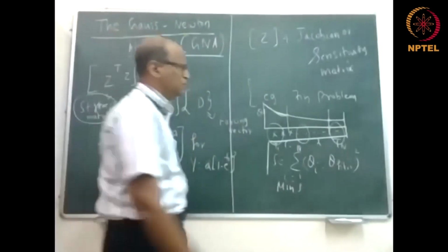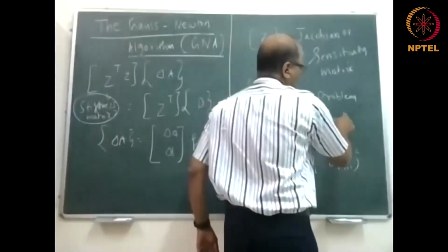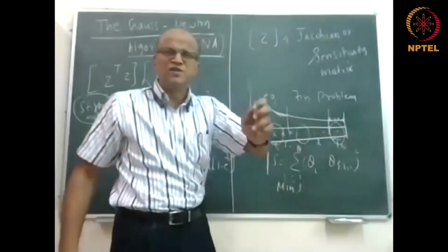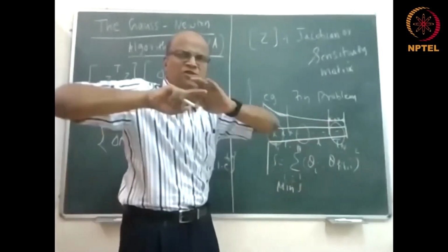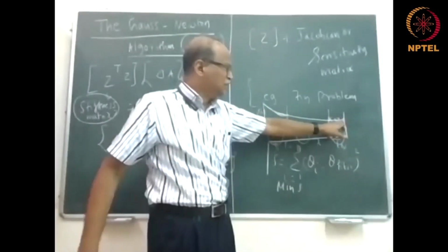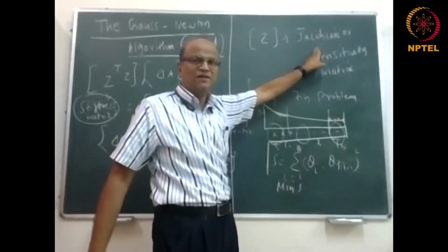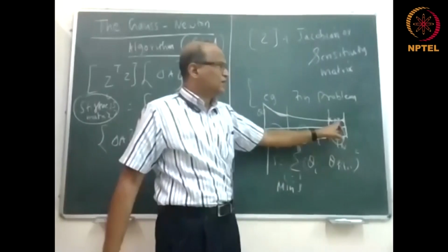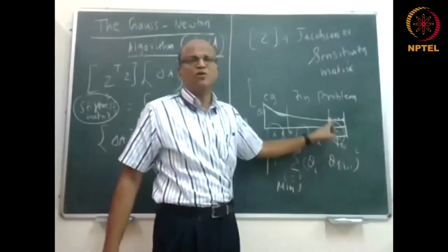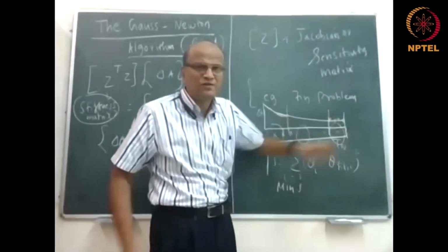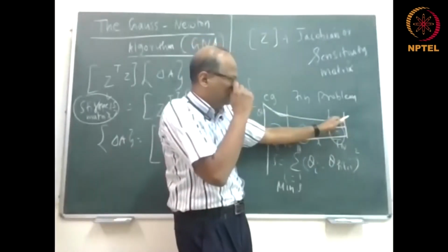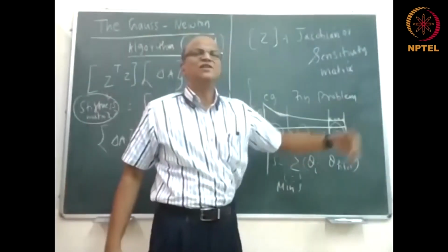Therefore, if you have 8 thermocouples and you have placed all the 8 thermocouples here because it's easier to measure here, this means you are a very good data scientist, but you have absolutely no idea of heat transfer. This will give you a wrong value of h, because if you take the Jacobian, dou T by dou m or dou T by dou h will be a very low value. It is giving very low values because the temperature anyway is not changing.